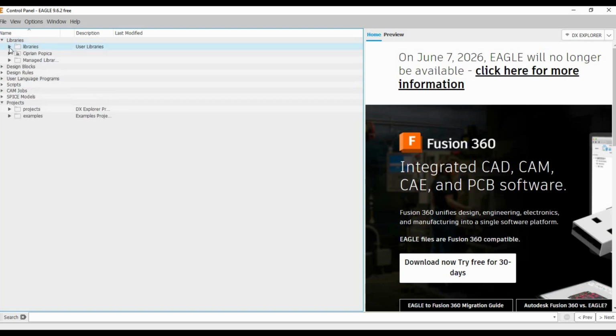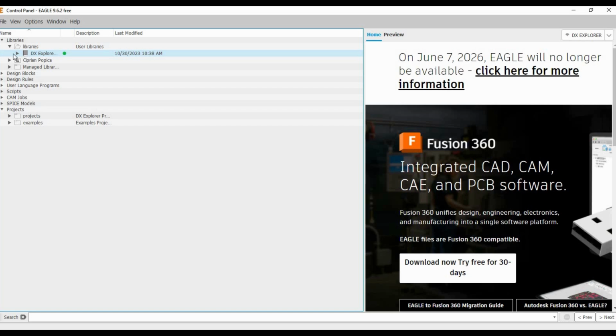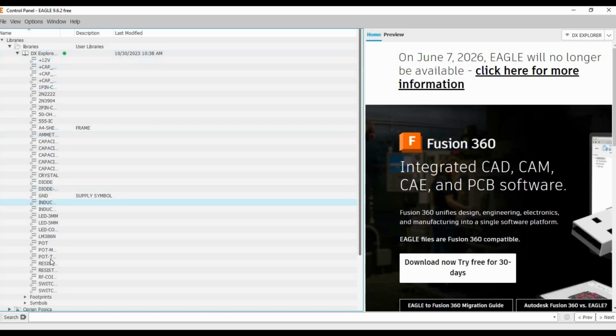Now in the libraries I created my own custom components library with the components that I'm using the most, just because remember, I'm using larger pads and also larger traces, so you can also create PCB boards at home using the toner transfer method.